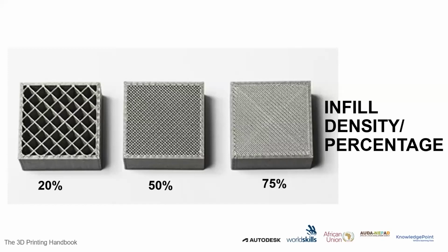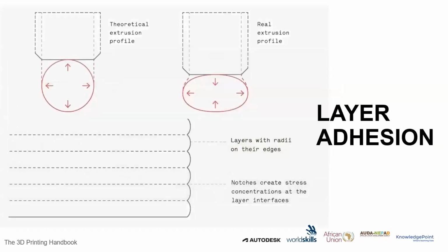Again, around 20% is a common infill density for FFF printing. Some machines or 3D printers vary between 15% and 25% for normal standard printing, and you can alter this in your settings.